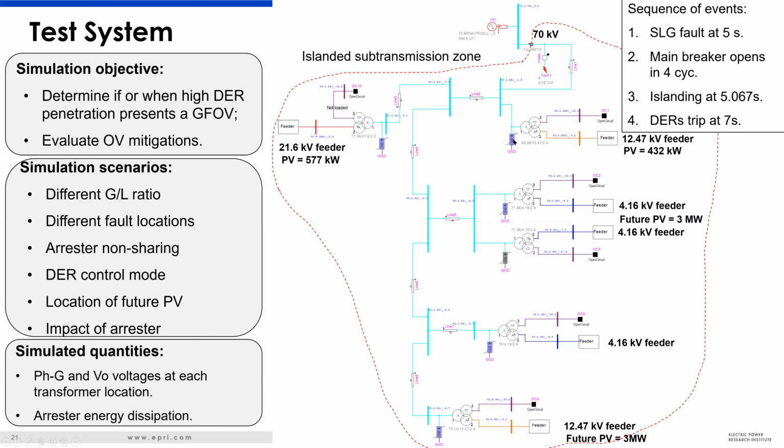And so this overvoltage at the existing level of PV is mainly characterized by motor loads. And again, in this case, the arresters did not conduct sufficient current to modify the voltage. And we increased to 21% with 6 megawatts of PV for future PV installations, basically. And it increased the overvoltage a little bit, but still we didn't see significant conduction by arresters.